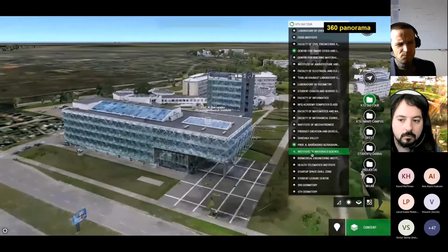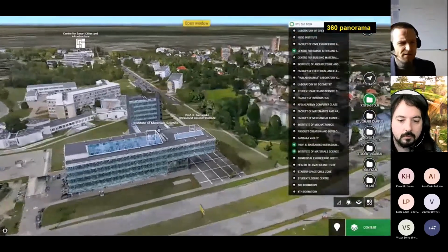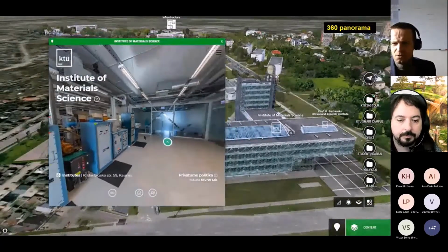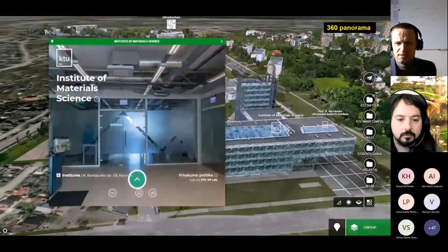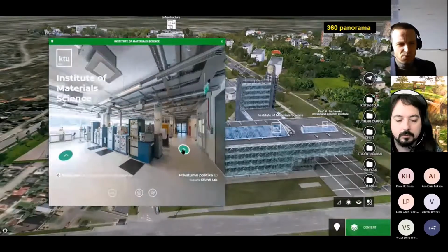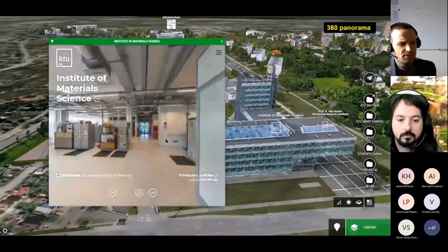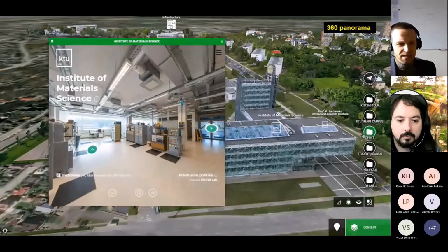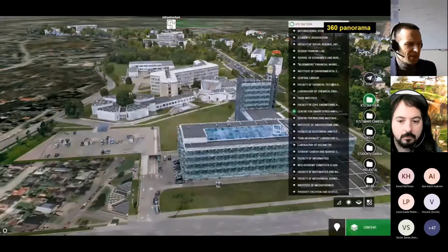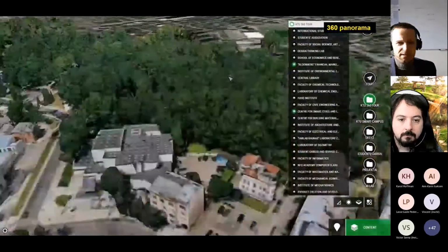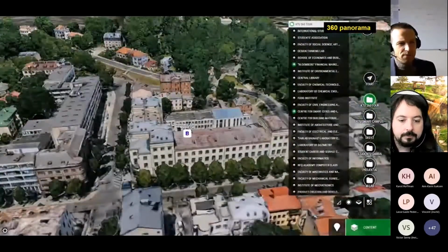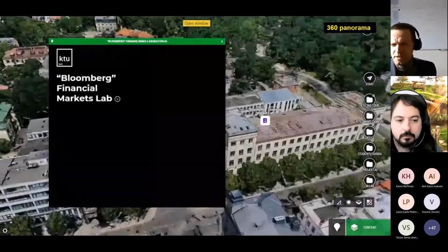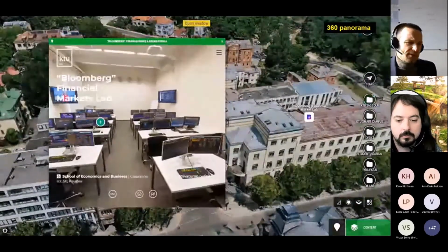we use, for example, reality capturing such as photogrammetry or LiDAR scanning, it is quite good outdoors, at urban scale, when we can get data by using drones, and we could get good accurate geolocation information from those devices.